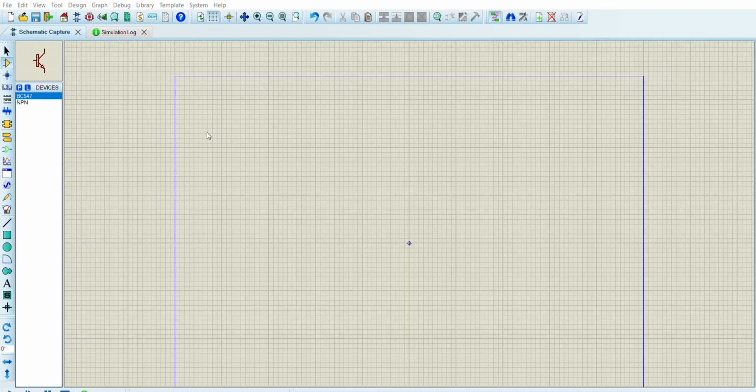Suppose we selected this transistor, silicon NPN low power bipolar junction transistor, 625 milliwatt. It can operate up to 625 milliwatt, 150 degrees centigrade. So this power consumption is also given, and we are selecting. You can select this one also. We are selecting this one, 5%. So we have placed it here, and now we have to plot.